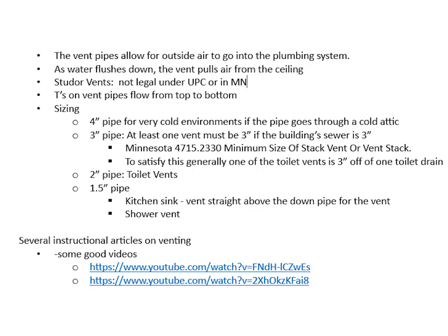Now let's talk venting. The vent pipes allow for outside air to go into the plumbing system. As water flushes down, the vent pulls air from the ceiling. Studor vents are not legal under UPC or in Minnesota. Tees on vent pipes flow from top to bottom.